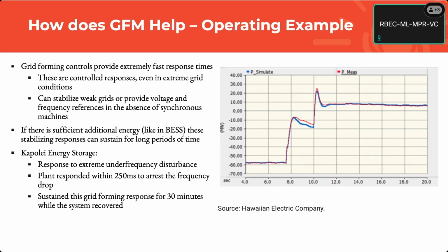Yeah, and there's pros and cons, right? Because a synchronous machine is governed 100% by physics even after the event. The good part of the synchronous machine is that it responds to the change in system. It basically resists change to the system. So voltage goes down, reactive power goes up automatically. It's resisting the change. If the frequency goes down, active power goes up automatically, resisting that change. That's a synchronous machine. But the synchronous machine is not a VSM, it's an SM. So it will do the swing, right? It will give you that energy, and then 100% of the time it will take it back.